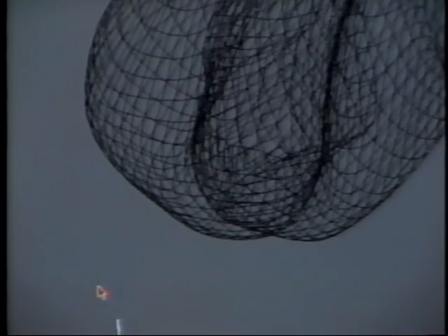Now in Duplicate Duplicator, we choose a number of copies and click on the base model and hair model when it prompts us to. There are other techniques for simulating surface fur that don't get drawn into your scene until you render in Mental Ray, but in terms of integration with the scene, matching the motion blur, the lighting, the shadows, and every other attribute of your surface, geometry-based details are often the best looking choice in your final render.